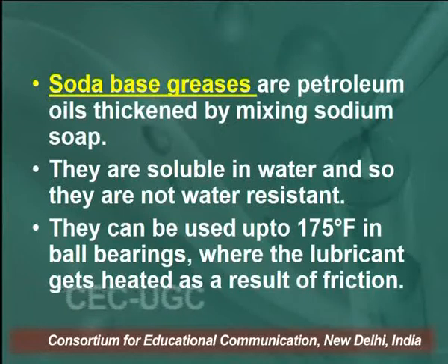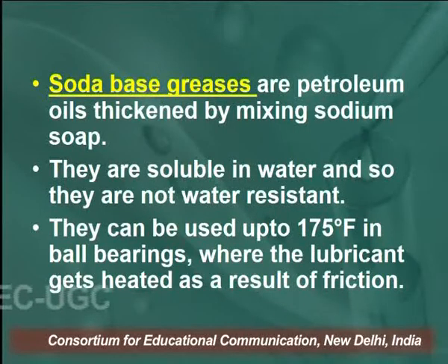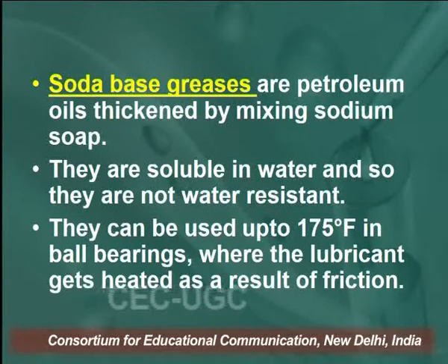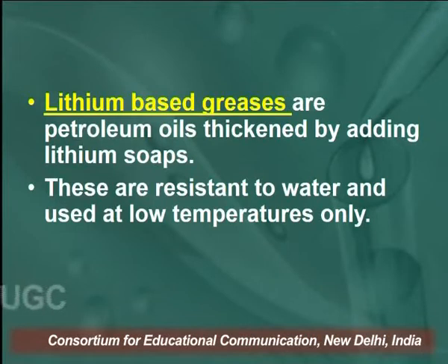Soda-based greases are petroleum oils thickened by mixing sodium soap. They are soluble in water and so they are not water resistant. They can be used up to 175 degrees Fahrenheit in ball bearings, where the lubricant gets heated as a result of friction. Lithium-based greases are petroleum oils thickened by adding lithium soaps. They are resistant to water and used at low temperatures only.